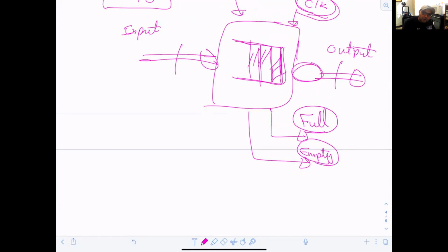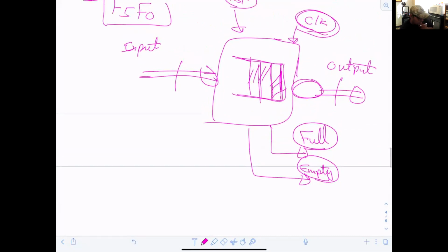What I'm gonna do, I'm having the luxury to push data inside the device. Then I need two things. One is associated with the input, and I call it push. The job of this push is that every time I make it high, whatever is written on this bus will be moved inside the memory.